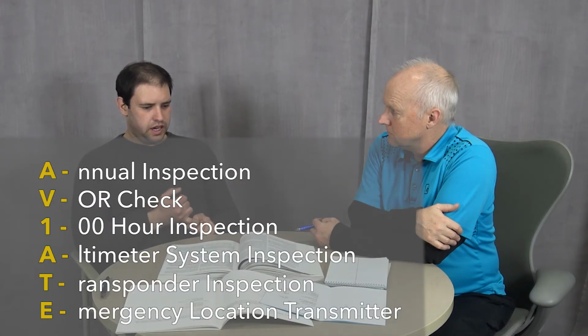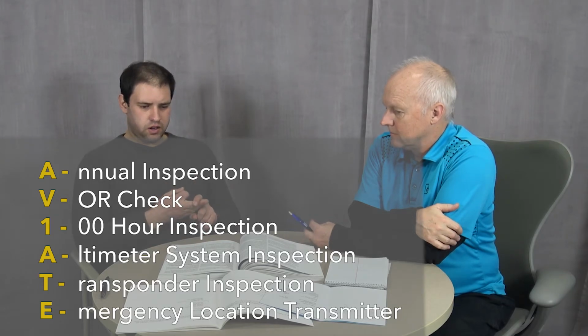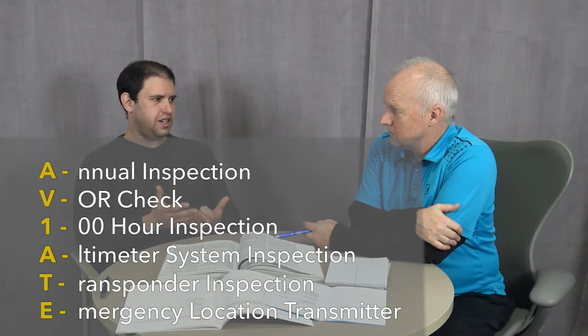So that completes our mnemonic of required inspections: Annual, VOR check, 100-hour, altimeter check, transponder, and ELT. And those are the inspections that must be done on the aircraft in order for it to be airworthy or to operate under certain flight rules. In the case of the Chief, the ELT is that brick that the intercom sits on top of when you're flying. That's correct.